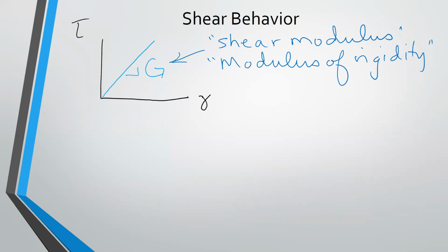And there's a relationship between these different material properties. So G and E, so your modulus of rigidity, your modulus of elasticity, and your Poisson ratio are all constants for a given material, but they can't be 3 arbitrary numbers. There's a relationship that relates them together. And that relationship is G equals E over 2 times 1 plus the Poisson ratio.